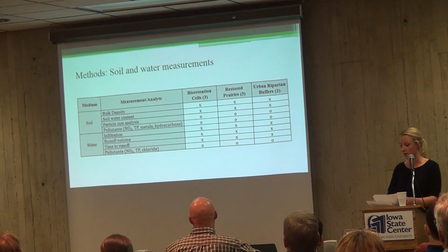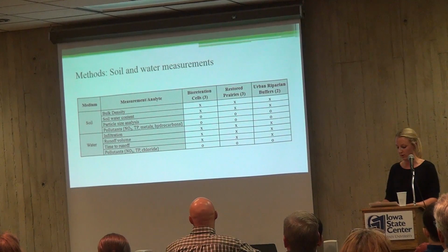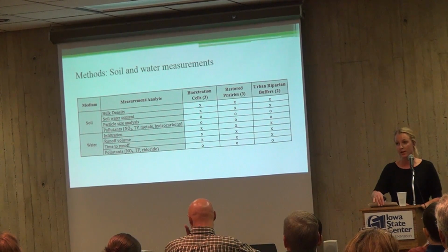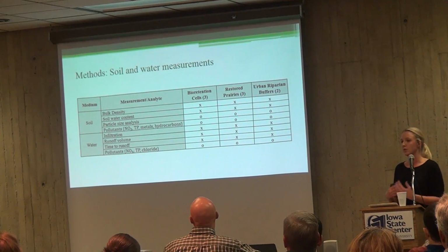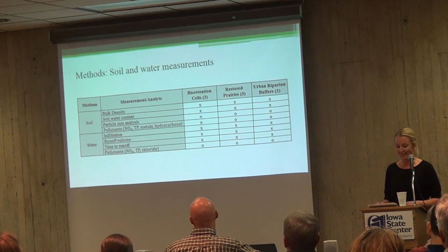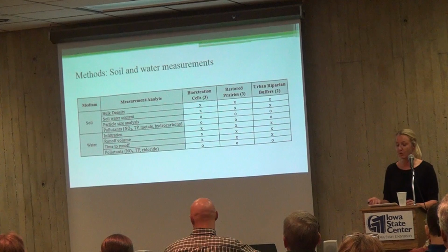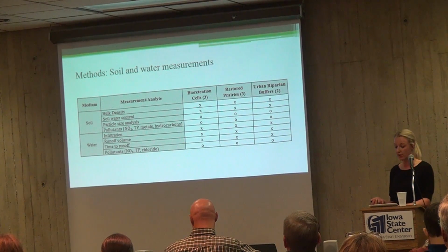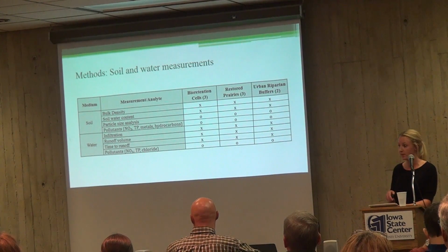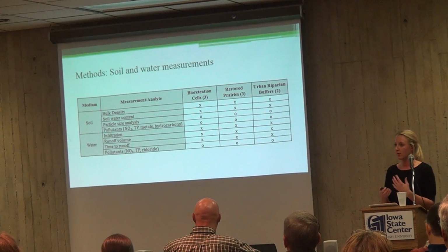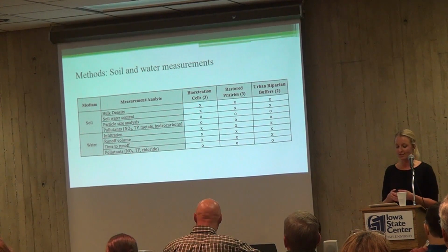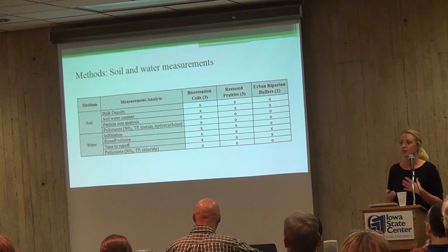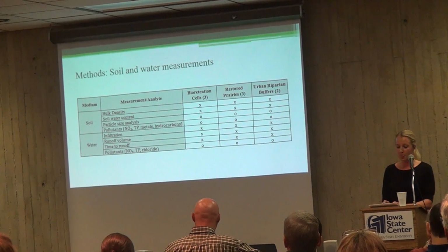Here's a chart describing our different parameters that we observed in our experiment. The X's indicate topics that I'm going to be addressing today, while the O's are topics that we're still evaluating. I'm just not going to get to them today. Surface soil samples were collected immediately adjacent to the location of the 3 infiltrometer tests at all the sites to determine the bulk density, the particle size analysis, and the soil water content preceding the infiltration measurements.